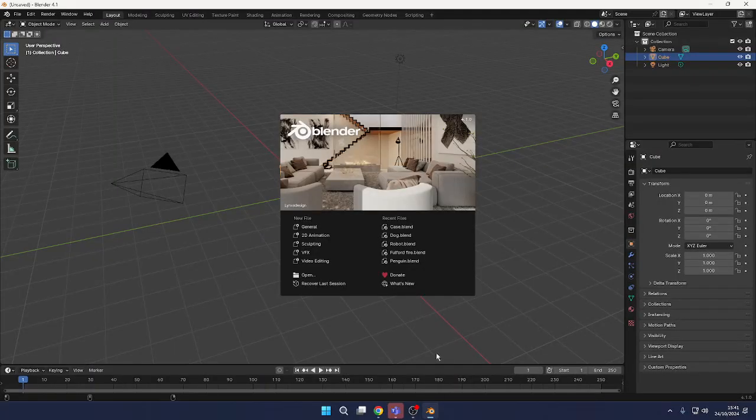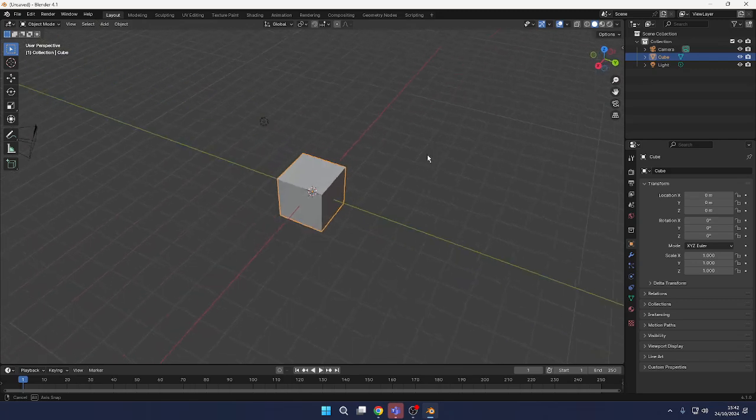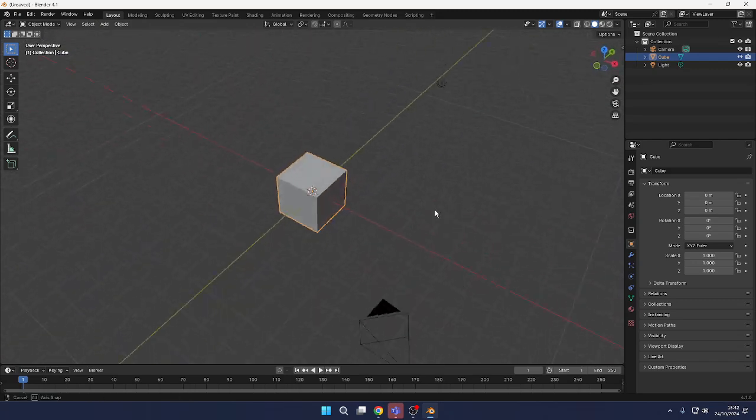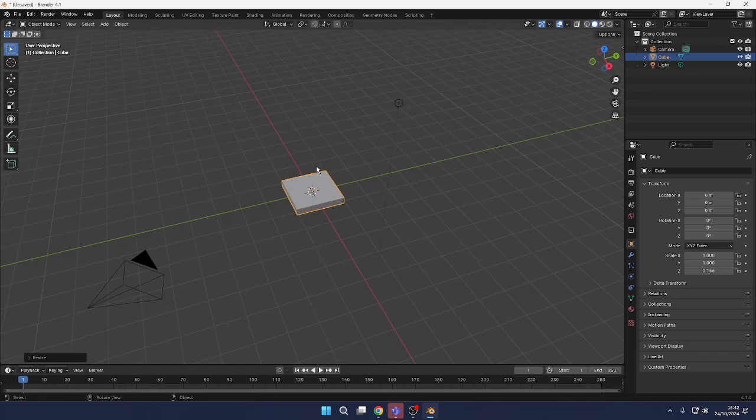So in Blender, you should have your keyboard shortcuts. We'll start with just the cube. I'm pushing my mouse wheel in and moving my mouse to look around. S to scale, moving my mouse, but I want to press Z and let go. Common mistake, people hold their finger on the key. So I'm not pressing S and holding it down. I press and let go, and I press Z and let go.